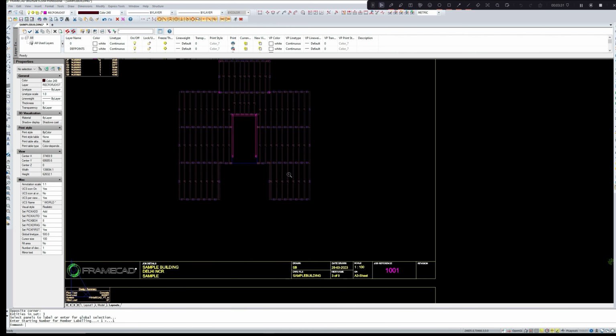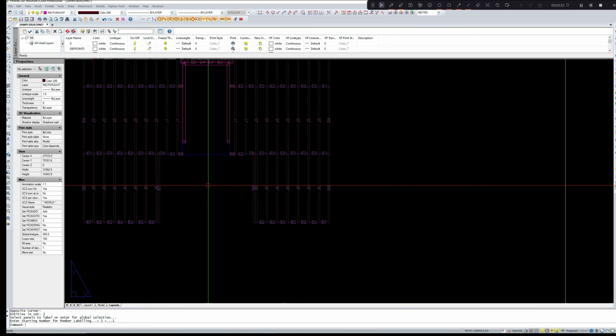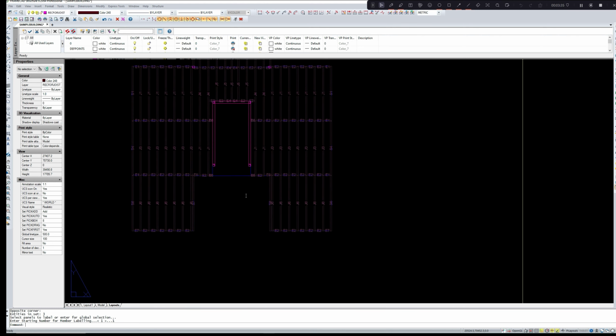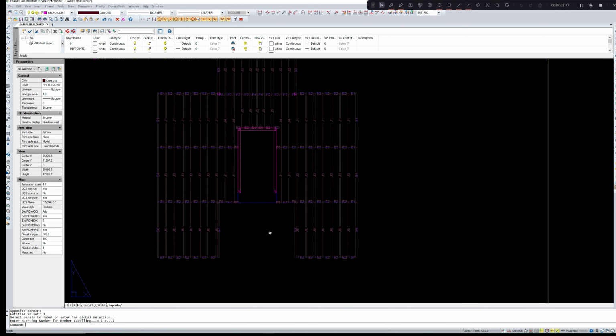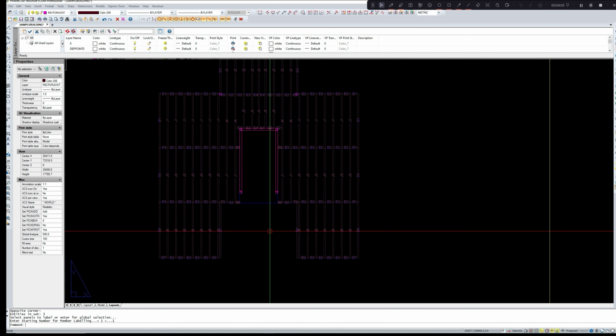Now we have to go to the joist. The joists are already leveled, but in the joist we have to assign the support line. We did not assign the support line because the moment we start assigning support line, the polygon we have created for creating the joist gets broken down. So we do not get any polygon for selection. So during the creation of the joist we did not create the support line. Now it is time to create the support line.